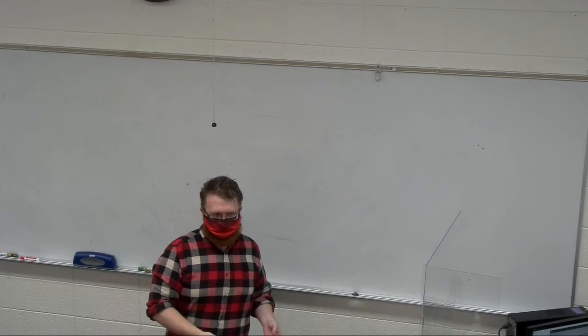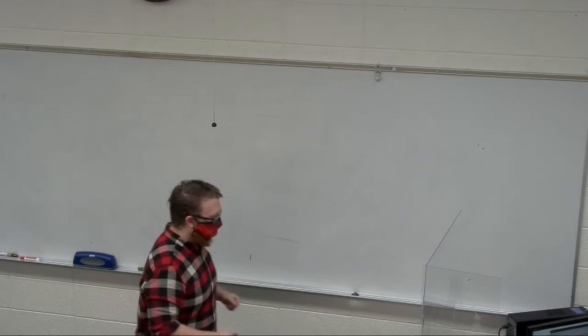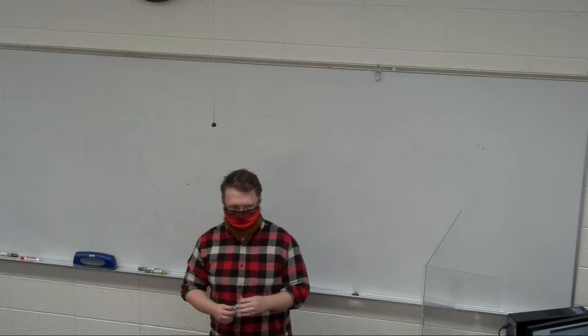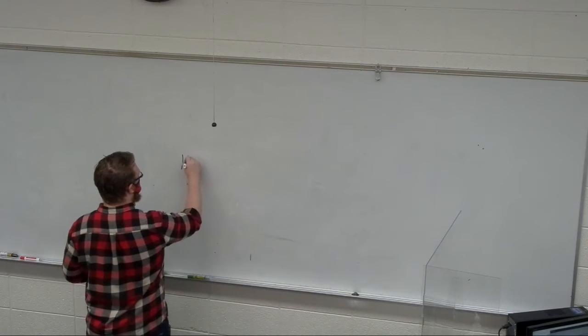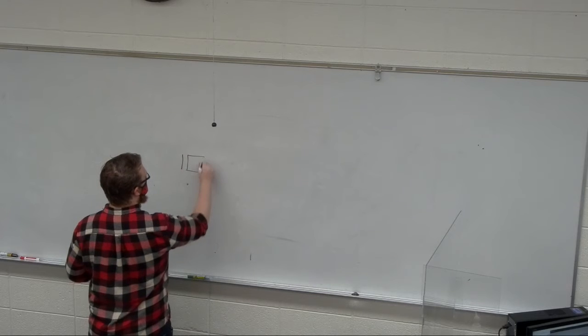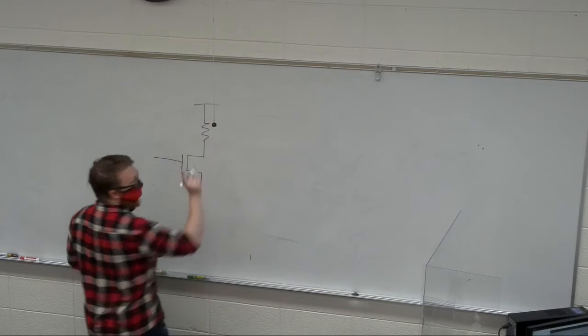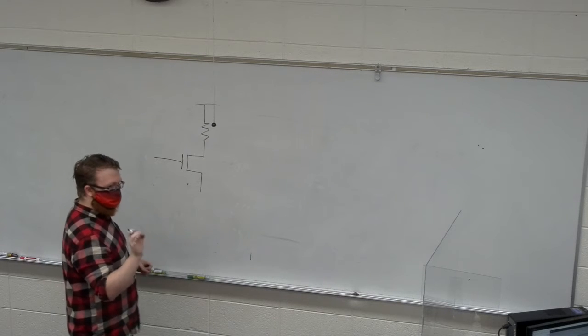A de-assertion delay is the opposite, when you go from 1 to 0. These times can be different because you could have a circuit with different drive strengths, right? So that's the same thing as propagation delay? It is not. It is linked, but it is slightly different.